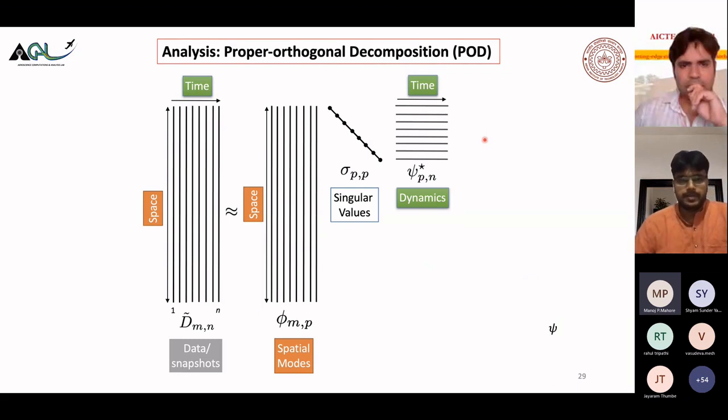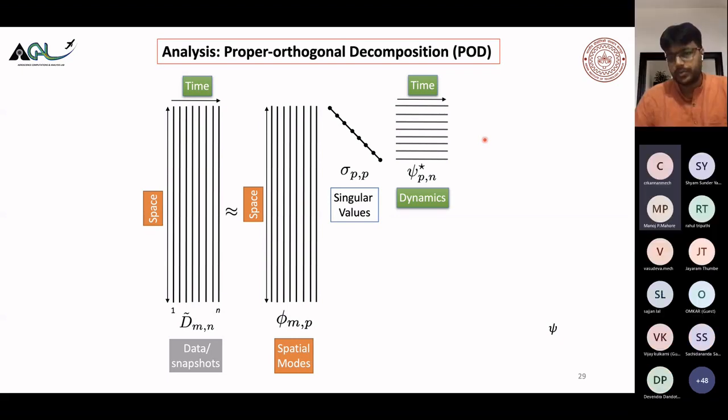Now I want to do some analysis. Because these are unsteady flows, we have several tools to study these kinds of things. One we just discussed is the spectral tool to find out what the frequency involved is. So is there any dominant frequency? And we found out that there is a dominant frequency of around 0.3, which is present in the flow.